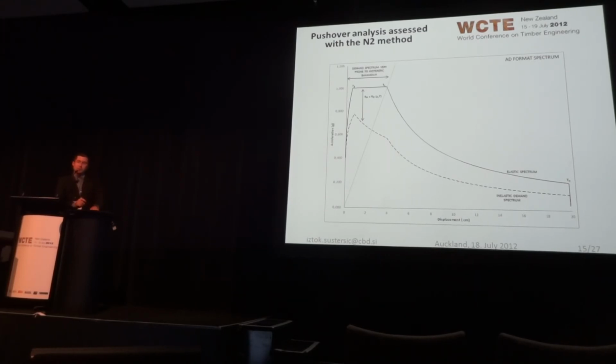And all the equations currently in the Eurocode are more or less devised for concrete and steel structures, which have more full hysteresis behavior. Timber structures exhibit pinching, slip, strength degradation, etc. However, if we're dealing with multi-storey construction, which has longer periods because higher buildings have longer periods, we are in the area where the demand spectrum is less prone to hysteresis behavior.